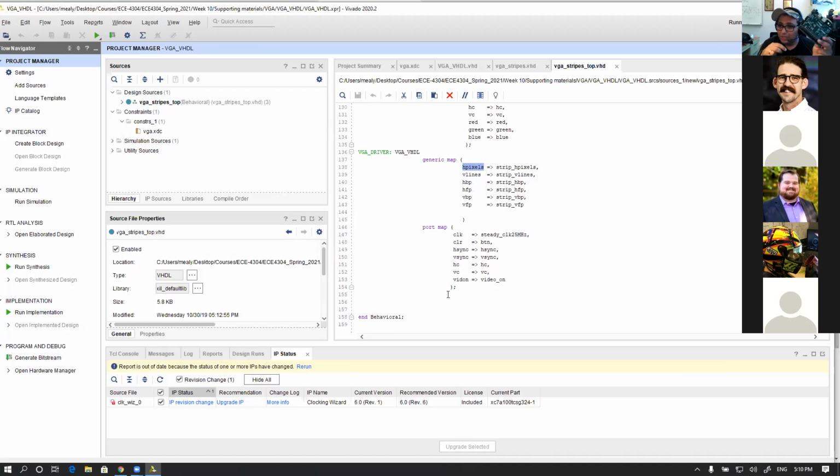Also, by the way, do you guys know that I can use the PMod? Everybody can see my screen? Yep. Do you see this? That is actually a PMod for UART. I can hook it here, and I can make it the official JTAG. I can hook it here.